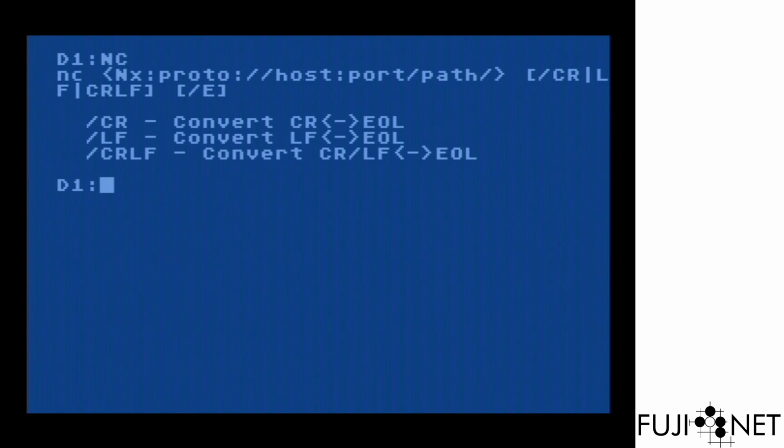Whereas the N device can potentially listen to up to 4 simultaneous TCP connections, each of them on their own IOCB, or a multitude of UDP packets from multiple destinations. All up to you. I will expand on this further, but I felt it was important to show some of the differences because people are definitely confused as to how the N and R devices actually work together.